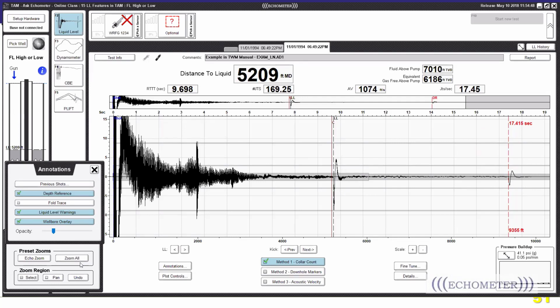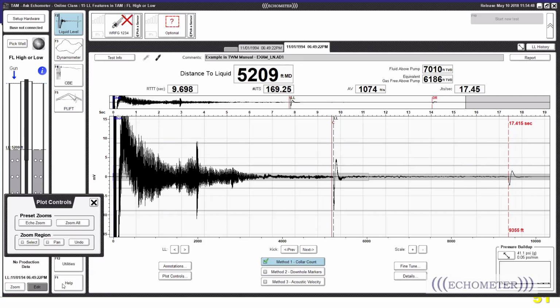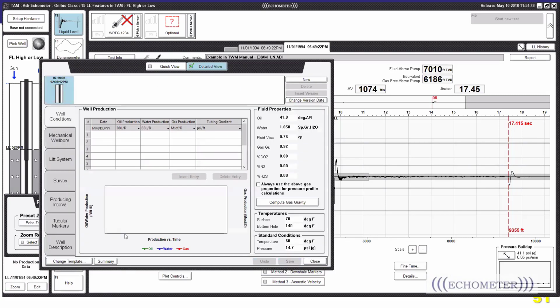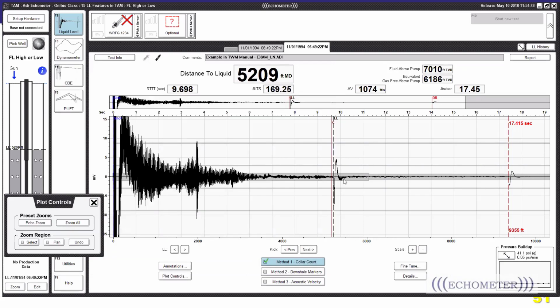If we review the well, hold on, we might need to review the wellbore schematic because we missed inputting some data, and we see we have a liner at 93.45. What's actually happening here is this kick is actually the top of a liner, and by not inputting the right information in the wellbore schematic, I might be doing a really bad liquid level selection, which will lead to a huge pump submergence, which is not right.